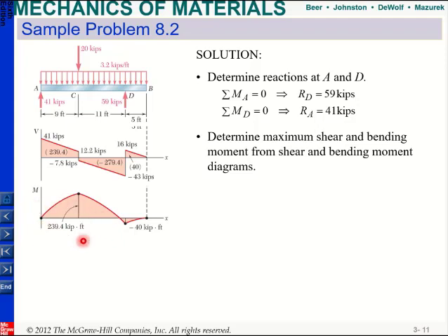When I compare, this is a very large value and this is very low. So when you look at it, I can say that at this point on the left, my maximum moment is almost 240 kip inches, and I have a shear force. And on this point, I also have 43 kips, but my moment is low, so you can also add your moment. Okay. Right.